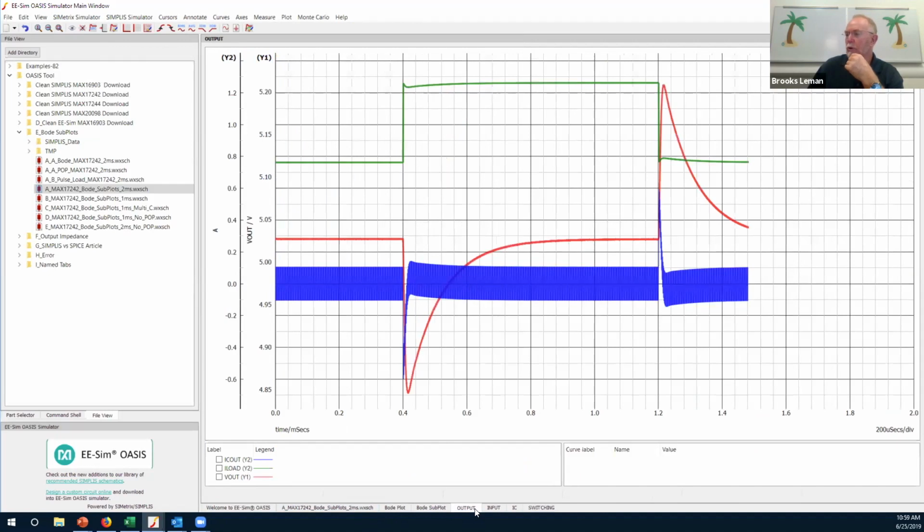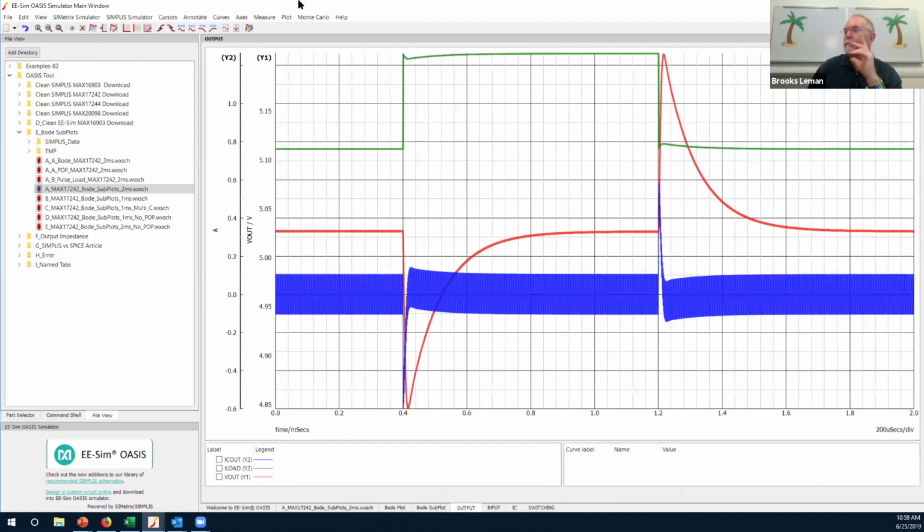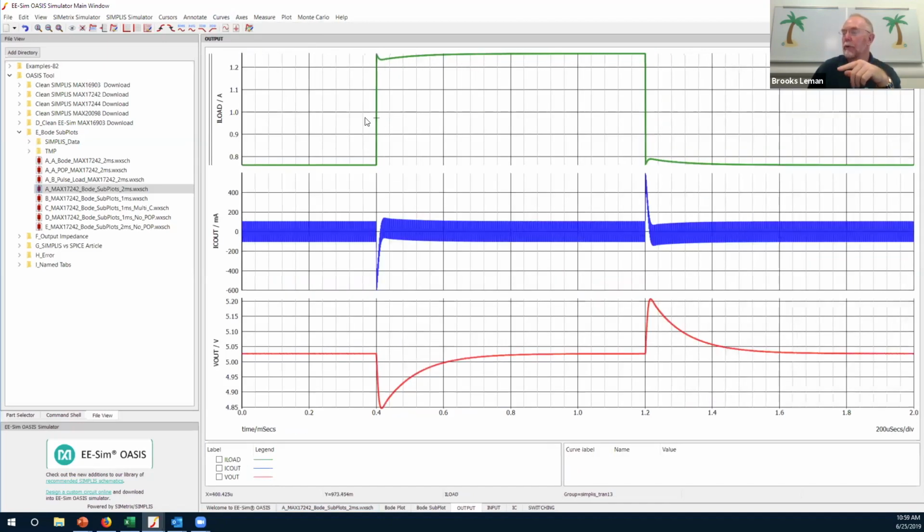If you have a lot of waveforms that show up in the same window, you can stack all the curves, and it simply creates a new grid per waveform. Okay. You can also move the waveforms around. You can create grids. You can create axes. In this case, I'm going to move this current waveform back down to this current grid, and you simply do that by selecting the grid that you are migrating to, selecting the waveform and curve.